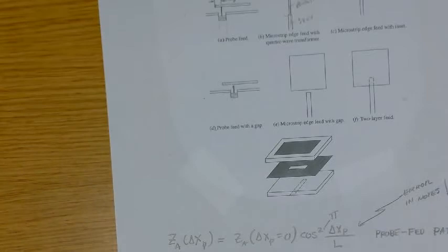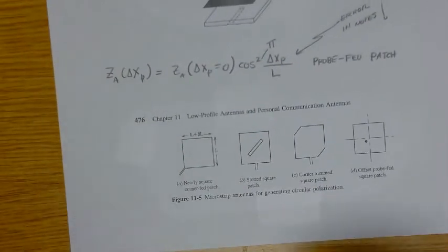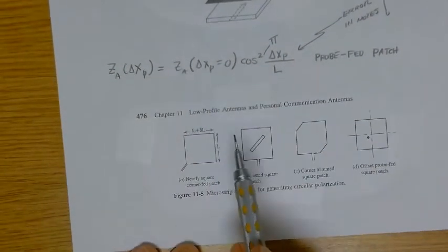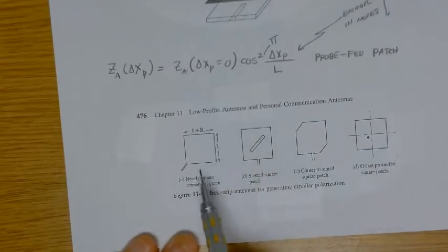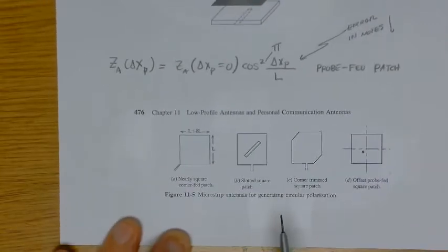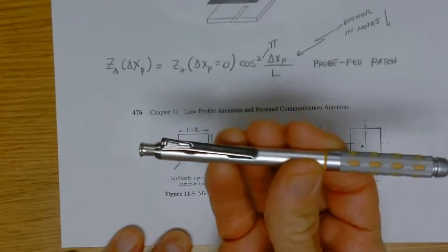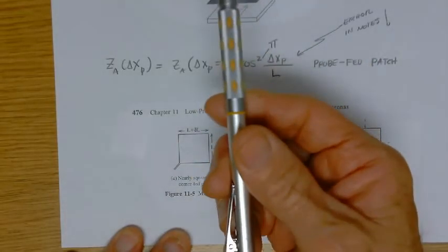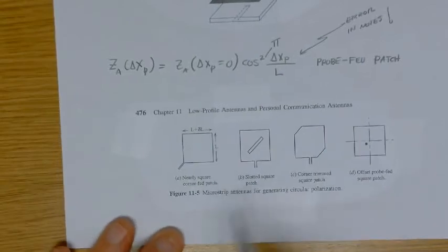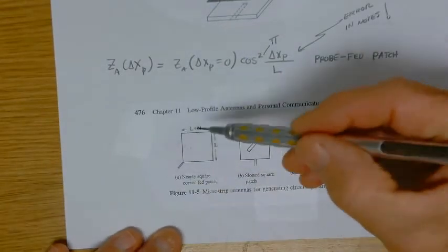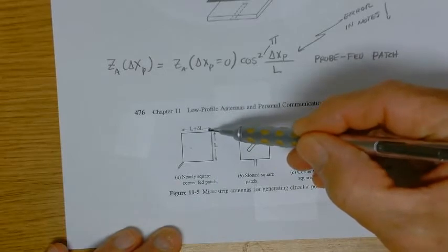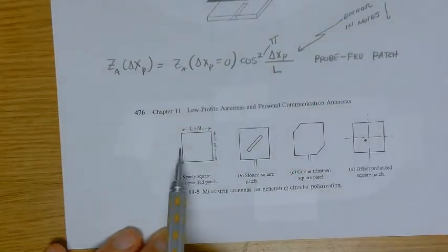Okay, page 4. Just keep pushing here a little bit, get through these notes. Down here, before we pursue this concept a little further, here are some interesting designs for creating circular polarization. How do you create circular polarization? Well, you need an electric field in the x direction and an electric field in the y direction, so this needs to be a radiating edge, and that needs to be a radiating edge. So you need to excite fields running this way and that way.